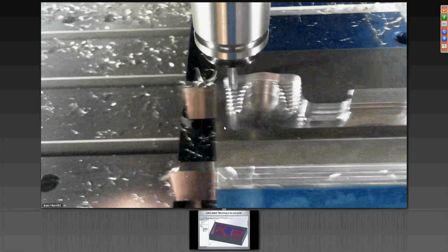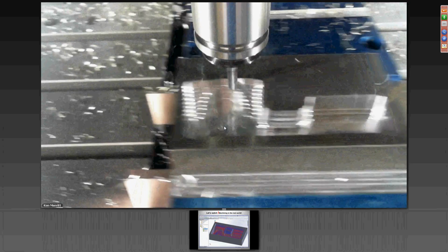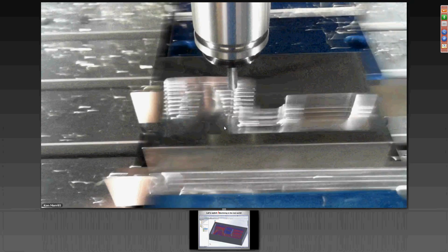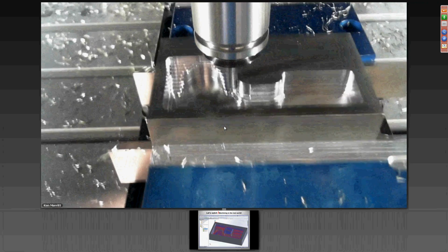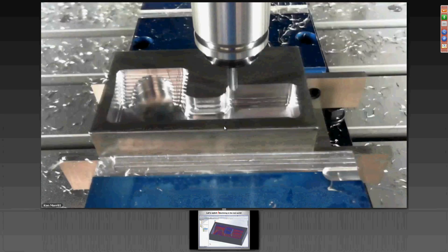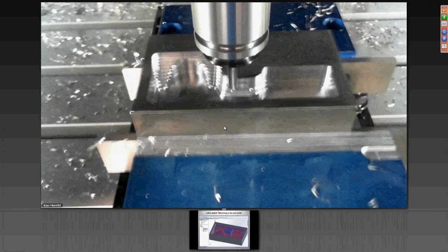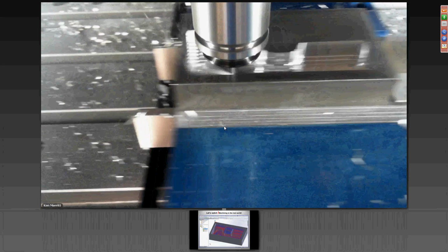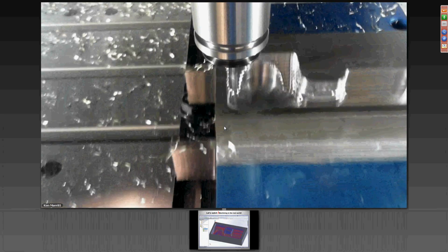And so you can see very quickly we're removing all of the shape inside this cavity and preparing it for the finishing tool. Now, one of the things that's very, very important about this, the consistency of that scallop carries a lot more importance than a lot of people want to admit, and that is when we go to the finishing tool, one of the things that causes us to have to do what they call a semi-finished tool